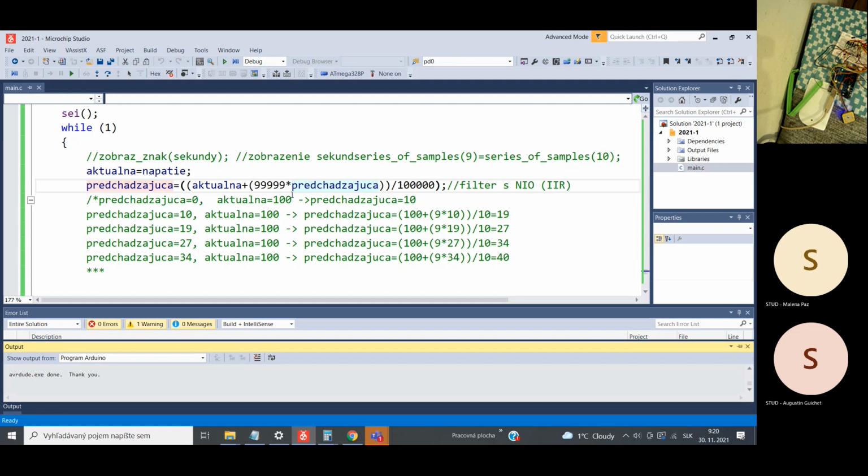But you cannot use it, for example, for throttle position in an engine, because you could change the throttle in a split second. In this example, for the gas throttle position, you should have these numbers lower, for example, like 100 and 101 or so, because you could push the throttle in, for example, 0.2 of a second, and it will be disturbing, because the engine will be very slow in dynamics.